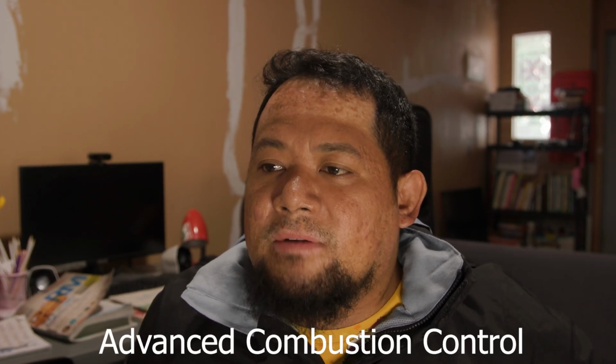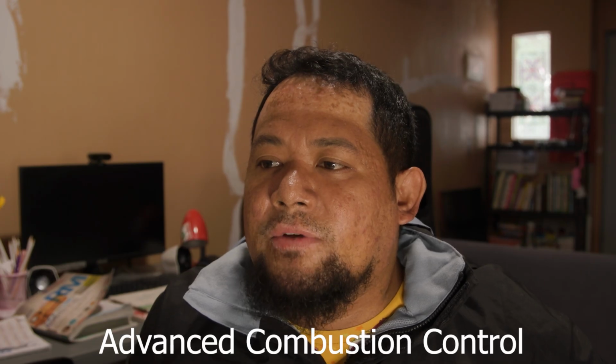And advanced combustion control, boiler automation. Advanced combustion control systems often use programmable logic controllers, or PLCs, ensuring proper combustion under various load conditions, improving efficiency and reducing emissions. Negative regulation technology. This technology draws gas into a premix combustion system, improving combustion efficiency and reducing emissions. Variable flow technology. This allows boilers to handle frequent fluctuations in system flow rate, making them more adaptable